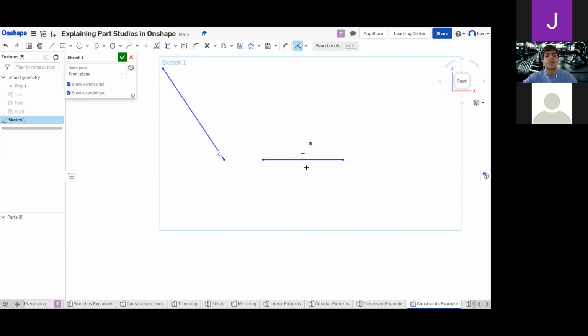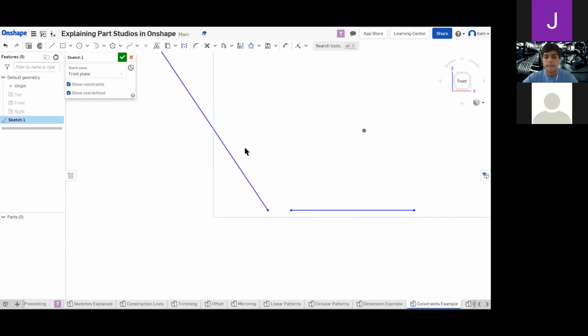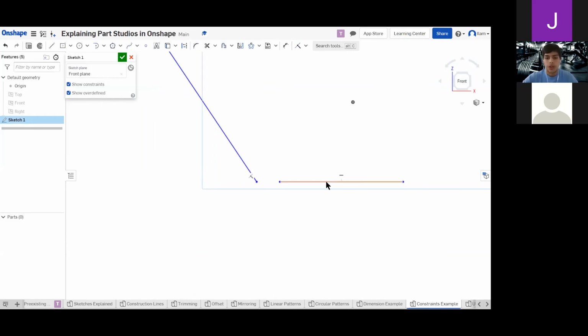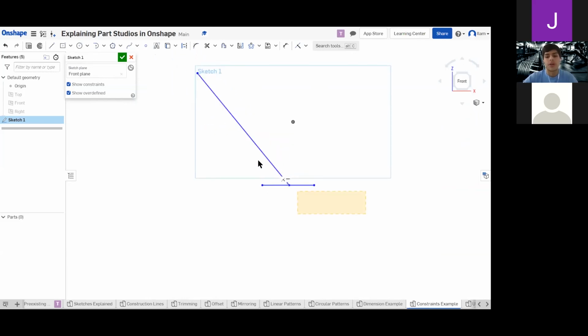As you can see, they're not necessarily touching, but they're basically on the same plane with each other. So if I were to move this one down here, let me move it down a little more so you guys can see better. There, that's where it's touching. So a coincident constraint doesn't mean that they're automatically not moving. They can still move, as long as they're along the same axis as this line, they are considered coincident.